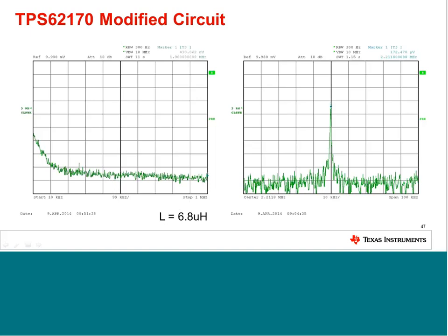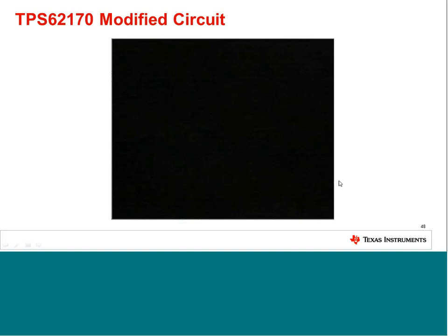If you look at the spectrum in the sensitive area I have shown here, you're not seeing anything anymore because the switching frequency is just above it. The switching frequency itself is very stable and has a clear line here and not a wide body. And if you connect this to the sensor, it's clean.